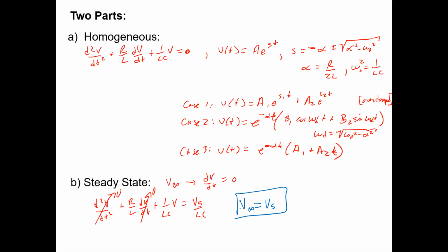What that means in the series RLC circuit is that all of the voltage drop eventually takes place over the capacitor. Because with a series circuit, when everything dies out, the inductor turns into a short, but there's no current going into the capacitor. The capacitor is an open, and the open rules a series circuit.